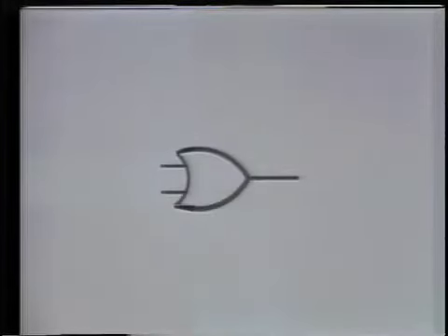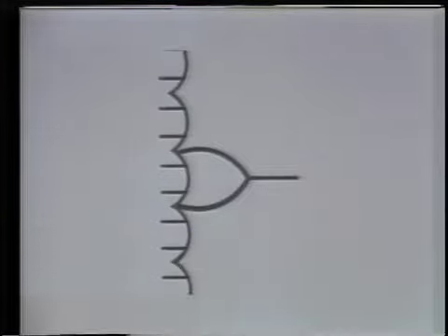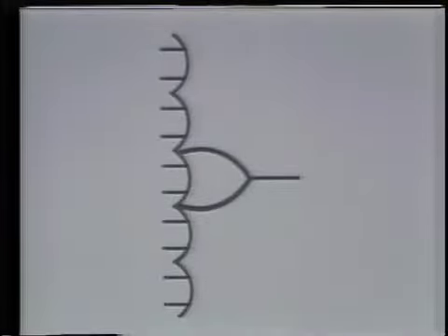If we have more inputs on the OR gate symbol than we have room to draw, we use a symbol like this. You can see there's quite a similarity between this and the AND gate as far as the technique that's used to symbolize the increased number of inputs. We have ears drawn on the OR gate to accommodate the extra inputs. The artist may add more ears if there are more inputs. These curved lines typically have 2 or 3 inputs on each curve, and if we need more inputs, we put another set of curved lines above and below in order to accommodate the additional inputs.